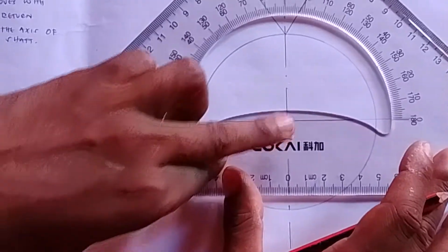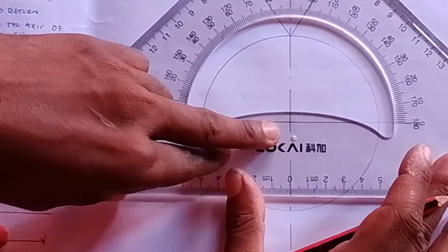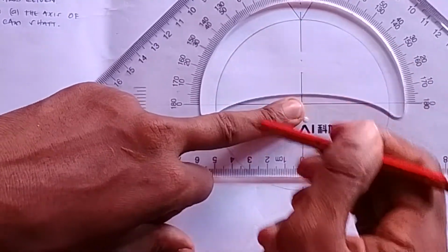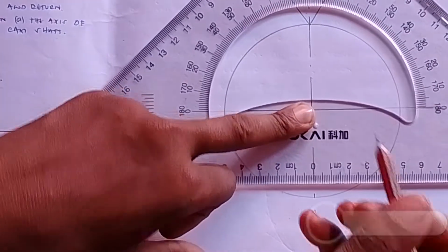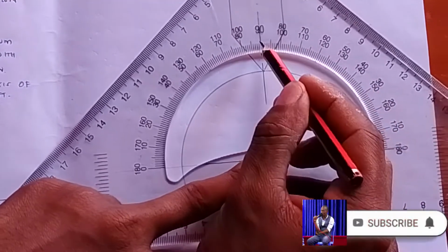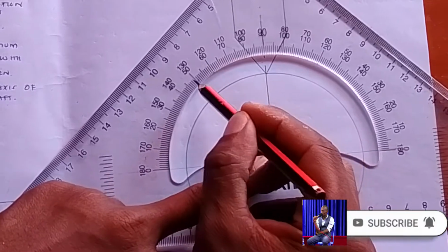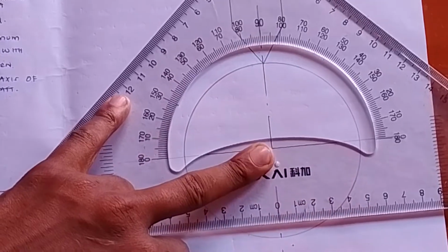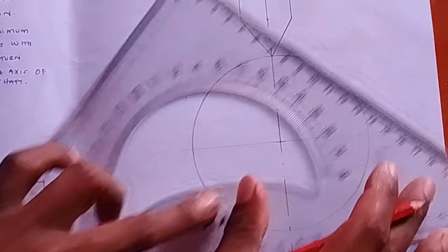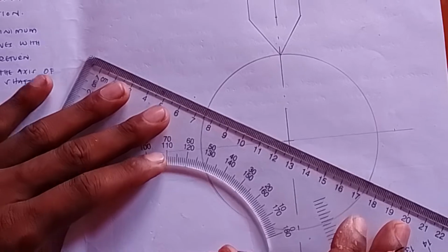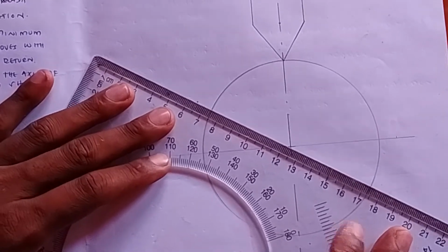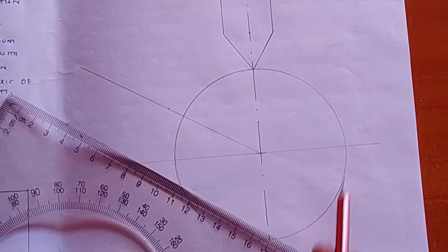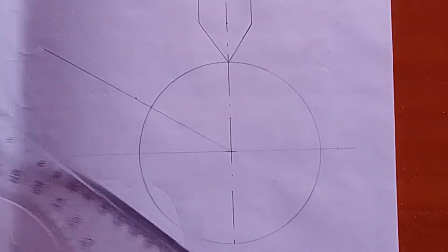So at this particular point, after you have aligned it with 90 degrees, it is like that. Measure going clockwise. I've said I will go anti-clockwise. I will not go clockwise. I will go anti-clockwise. So measure 60 degrees. So this is 0, 1, 2, 3, 4, 5, 6. At this point here, this is our 60 degrees. That is our outstroke, all the rise. So project a line that is exceeding this radius of the base line, like that.